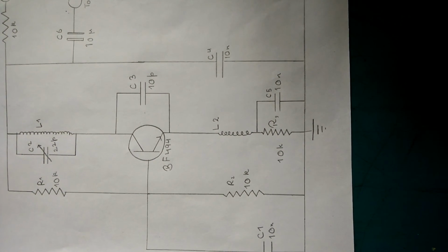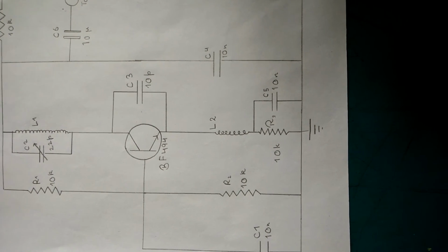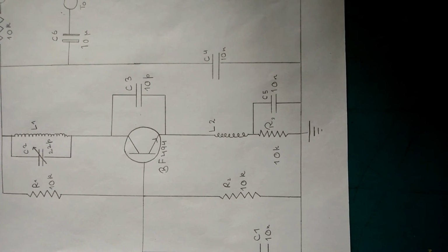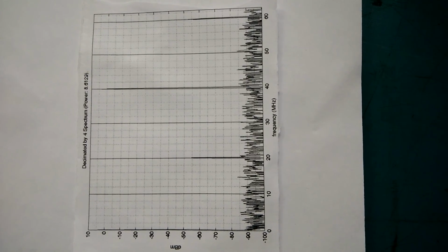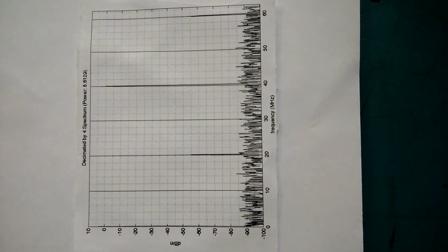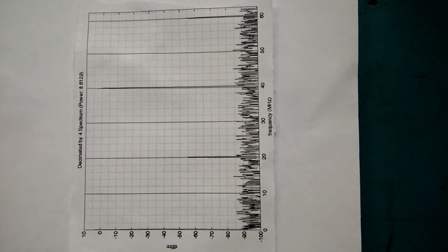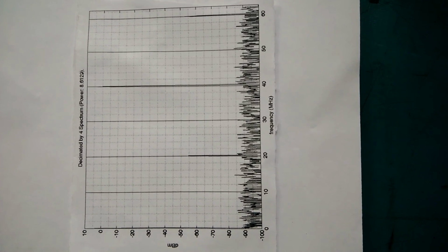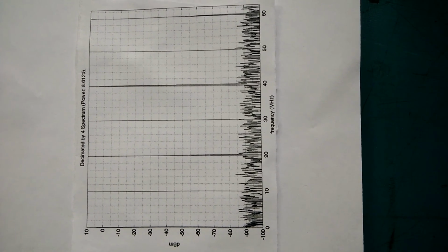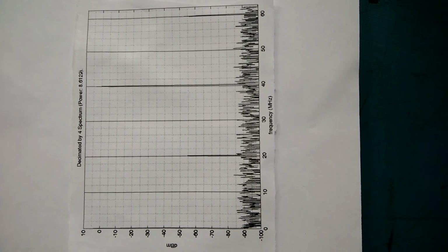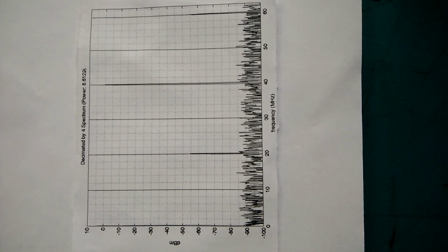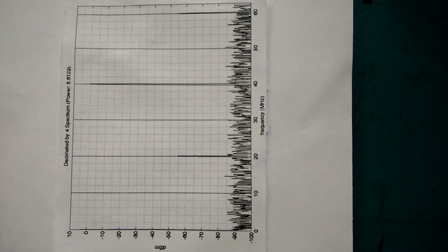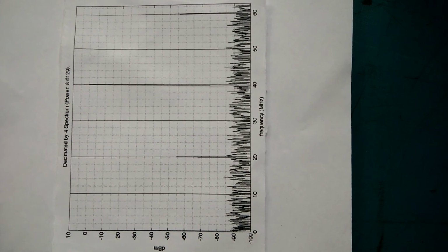Here, for example, is a 1 kHz signal represented in the frequency domain. Sampling the environment around us might yield something like this, although the numbers are not likely to match up exactly since FM radio is transmitted at higher frequencies than those shown here. As we can see, there are several peaks representing power in the transmission channel. Our radio receives all of this information and filters out the unwanted data. This can happen either in digital space through software or in the analog space through electrical components. The implementation for each is quite different, but the overall goal is the same: filtration.